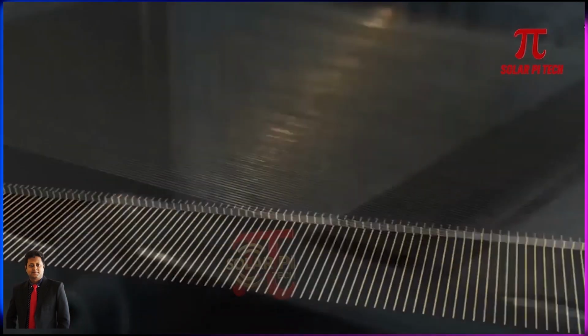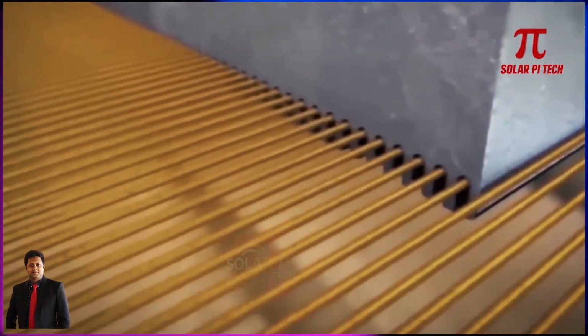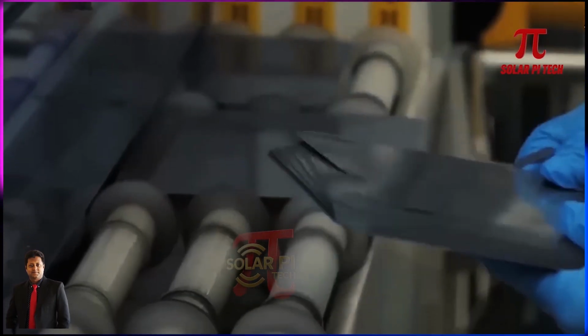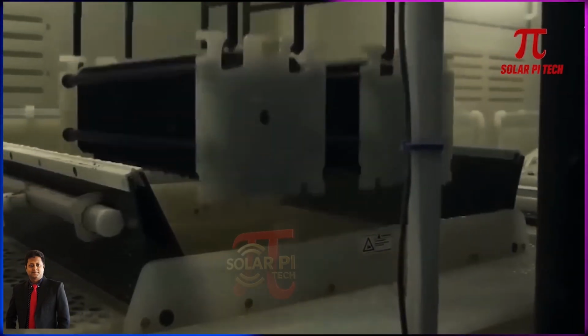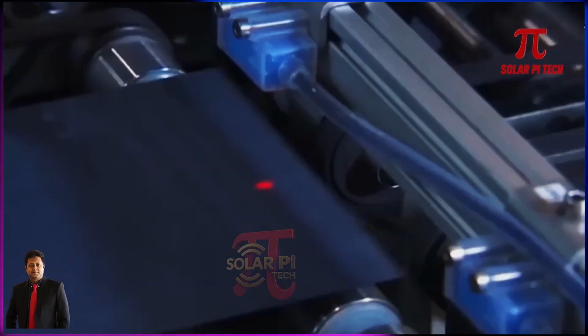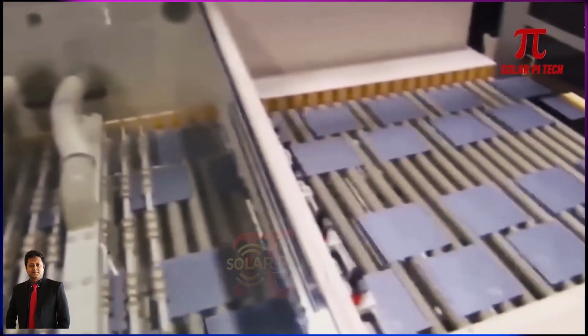The silicon ingots are sliced into thin wafers using a wire saw, a process that requires precision to minimize material loss. These wafers, typically less than 200 micrometers thick, undergo surface treatment to remove any remaining impurities and defects. An anti-reflective coating is applied to the front surface of the wafer to enhance light absorption, allowing for greater efficiency in converting sunlight into electricity, and the subsequent drying process ensures optimum surface cleaning.